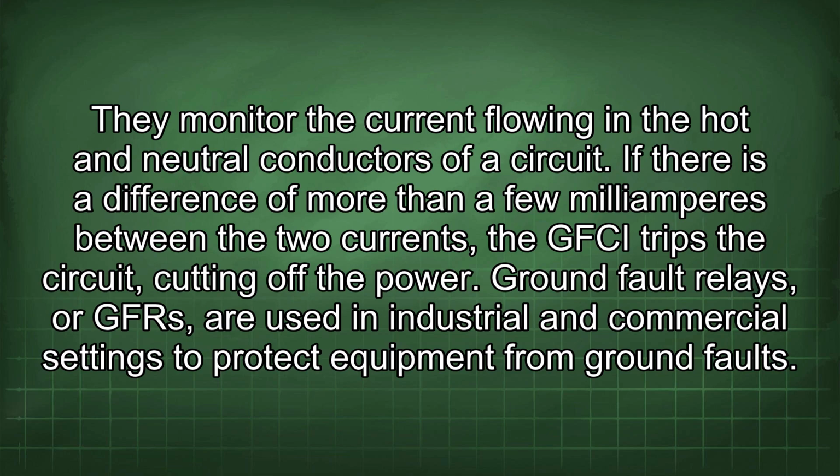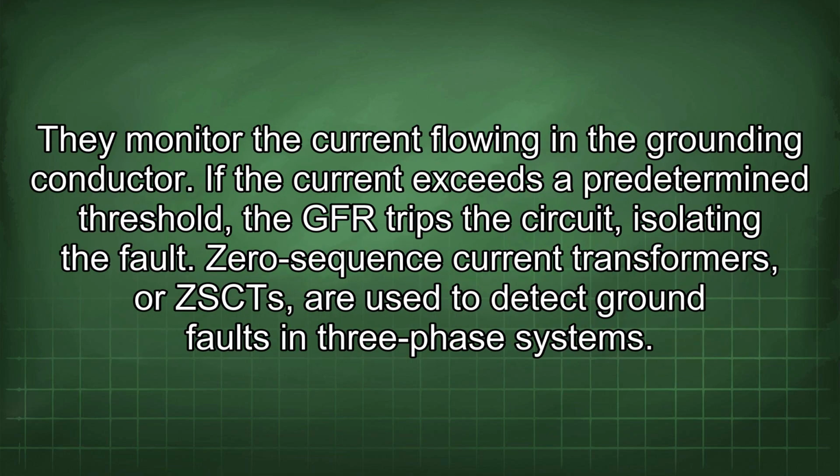Ground fault relays, or GFRs, are used in industrial and commercial settings to protect equipment from ground faults. They monitor the current flowing in the grounding conductor. If the current exceeds a predetermined threshold, the GFR trips the circuit, isolating the fault.